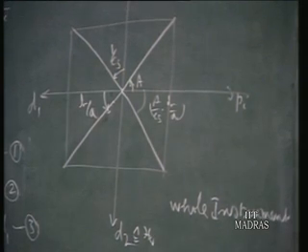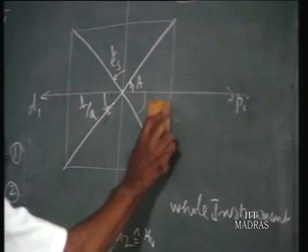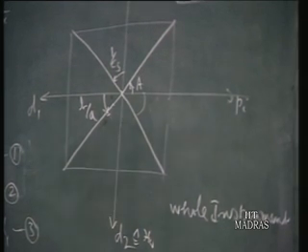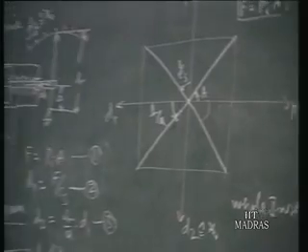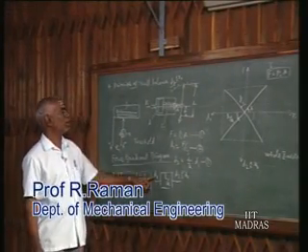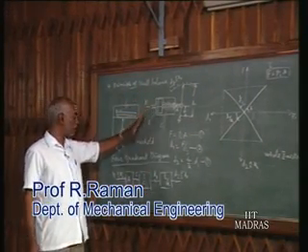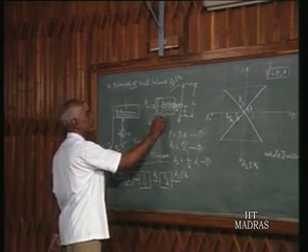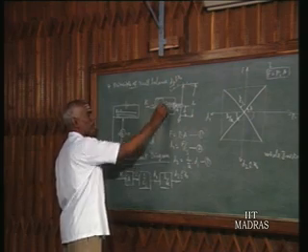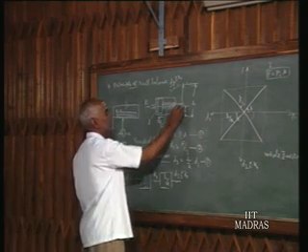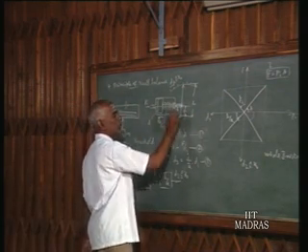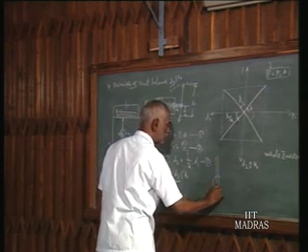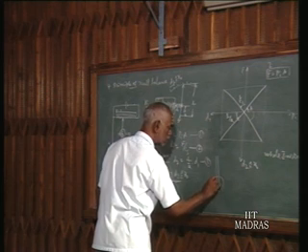We will see how to make use of these 3 quadrants here to fix the amount of error due to error sources. What are the error sources of the instrument? For that purpose we should know what the signals are, and the error source should be of the same nature as the signal. Now we have got the signals as force and displacement. So naturally friction force FF is an error source for the force signal, and we have got some play. This is a hole. Suppose I draw a bigger view of this. The pointer comes like this and the hole is somewhat like this. Yeah, this is our pointer.